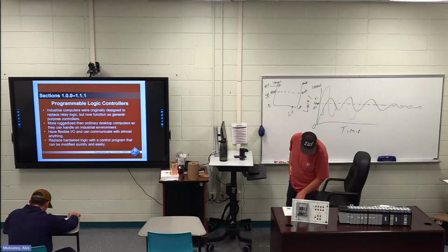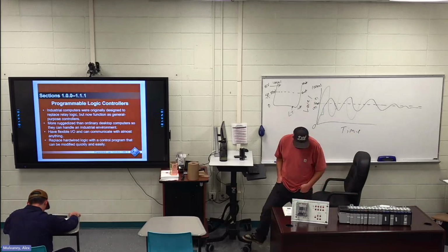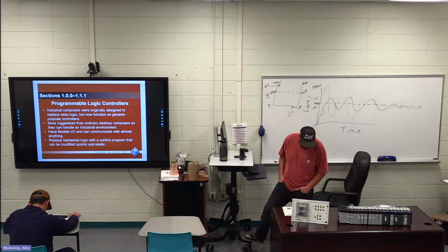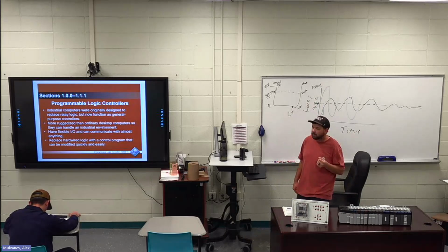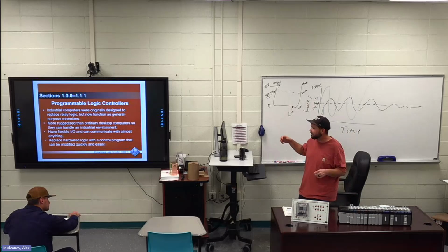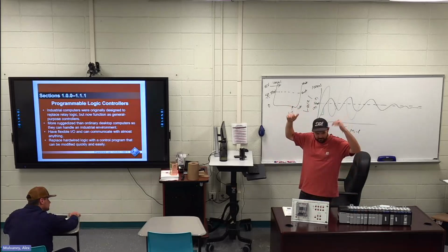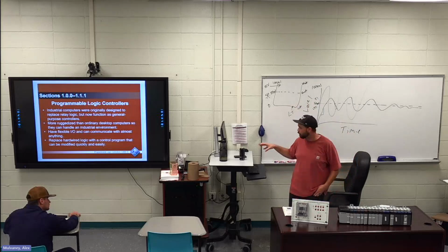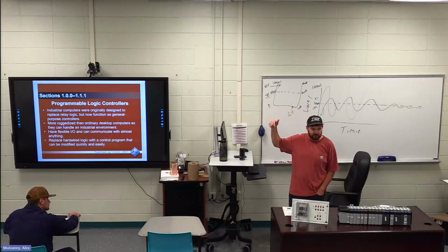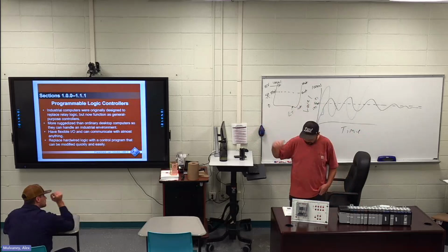A programmable logic controller is a microprocessor control device similar to a computer that can be programmed by a user to perform specific tasks. All right, you guys have been learning how to do a lot of ladder logic and put circuits together using that ladder logic, right? So these PLCs have brains and the programming can be done in ladder logic. Your inputs are your push buttons, and your outputs are your valve controllers or lights.